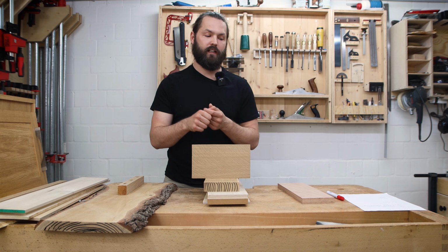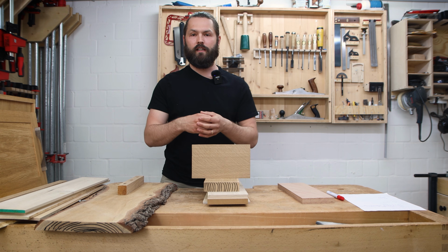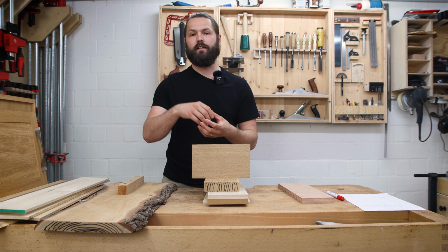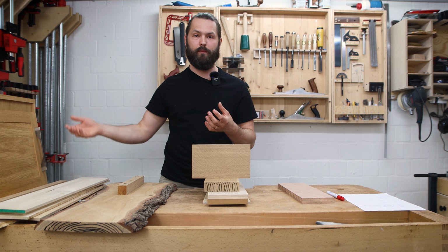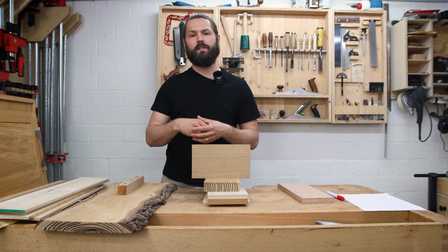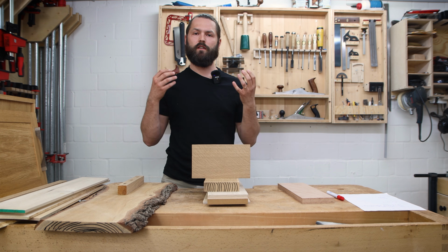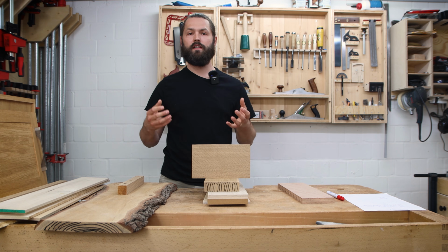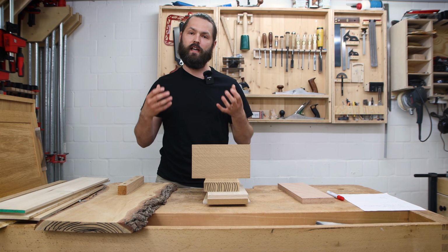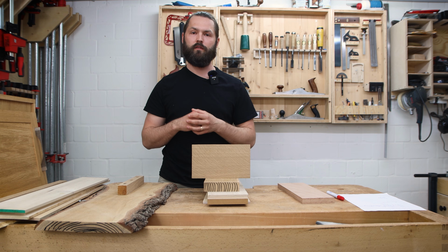This can be done in a number of ways. It can be by leaving a gap, in the case of a drawer. It can be by a joint that allows for expansion and contraction, like a tongue and groove where the panel can float, as we have seen in the frame and panel construction. This can also be a sliding dovetail. You might have heard or seen that. This can also be just an oval screw hole where the screw can move in the slot. If you need a very stable panel or don't want to account for wood movement, plywood might be the way to go, and you can even make your own plywood.